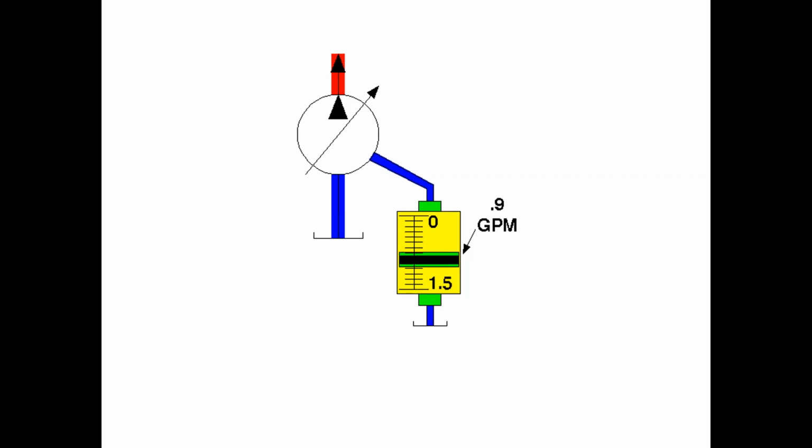A lot of people think that a pump is like a light bulb, that it works great until it breaks and then it's no good anymore. Well, that's simply not true. Pump wear is a very gradual thing, very easy to track. Yeah, there are catastrophic failures. It does happen, but it's usually pretty obvious when it does. We're usually going to make an awful lot of noise. It's often going to blow out the shaft seal and shoot oil everywhere, and it's not going to move anything, and pressure is going to be very low, but that's pretty rare.